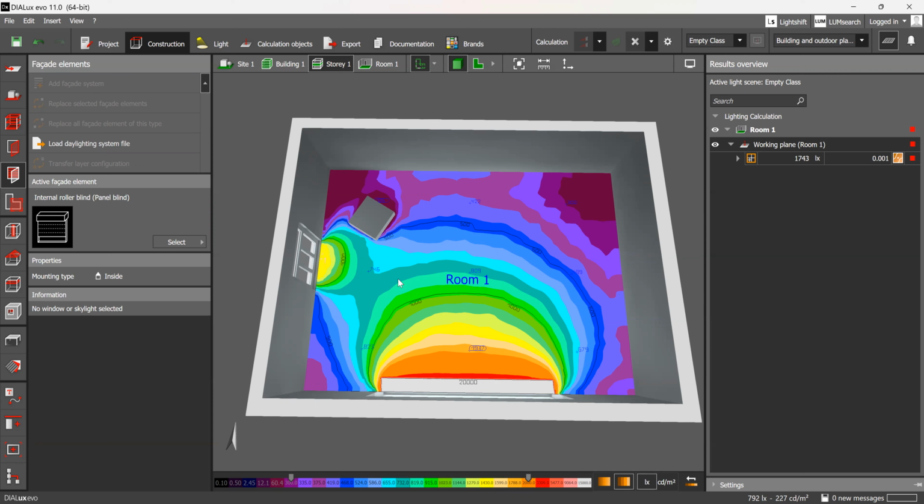Again, why do we use grids and multiple measurements in the room? Because as you can see in the false color map, the illuminance level in the front of the room is a lot, whereas in the back of the room, in some points, it can reach below 50. This really dark one is at 12. That's why we have grids in the room, and that's why we measure things. Right? One of your classmates asked about measurements with artificial lighting. I can briefly go through that after this, and then we will use the lux meter to carry out a cool experiment. Is there any question on DIALux Evo?